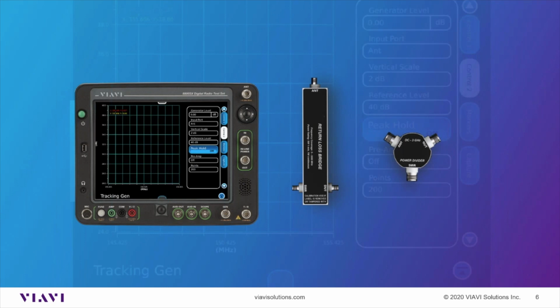Like I said, you'll be measuring in dB instead of VSWR, but you can convert that to VSWR. You can also convert that to a percent reflected power that you would have if you were transmitting live. So there's more than one way to get there. It's just a little bit easier on the 8800 because the scale's already there for it.